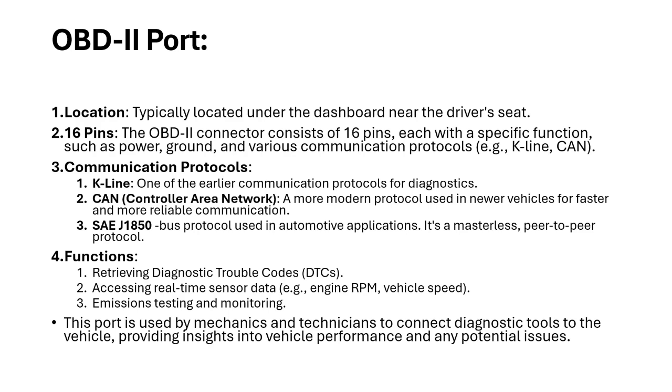Easily, the emission tester can check the emission level of the vehicle by simply connecting into this port and reading the appropriate data. This port, as we already discussed, is used by mechanics and technicians to connect the diagnostic tool to the vehicle and get the performance and any malfunctioning of the component.